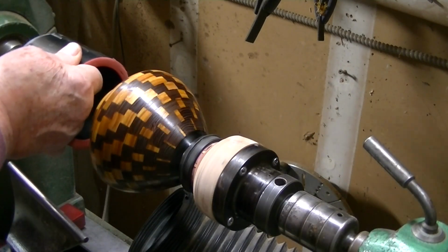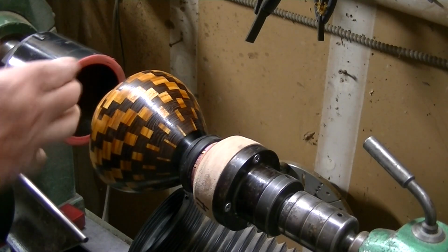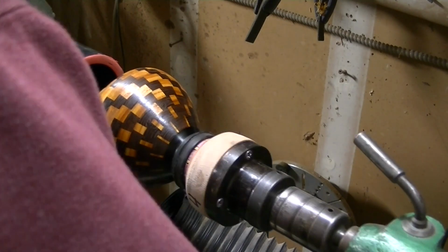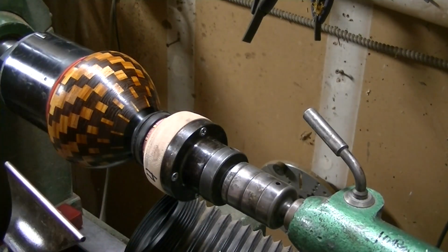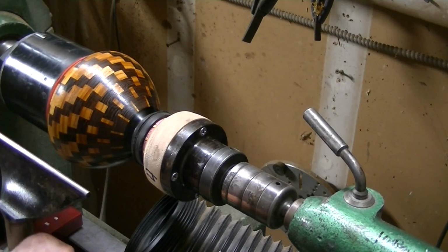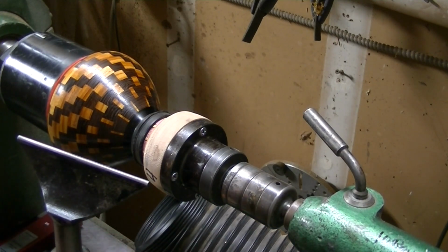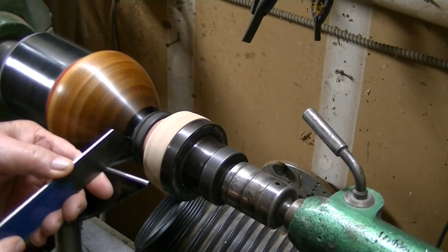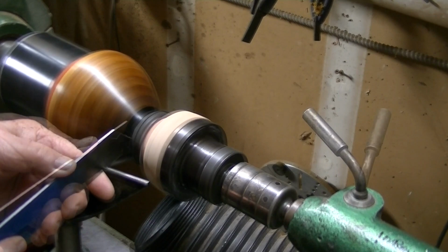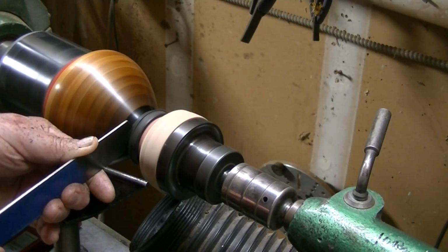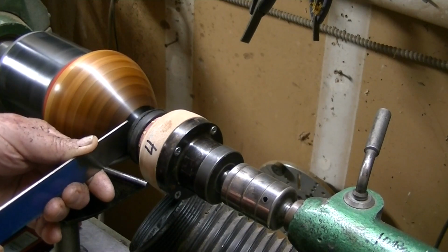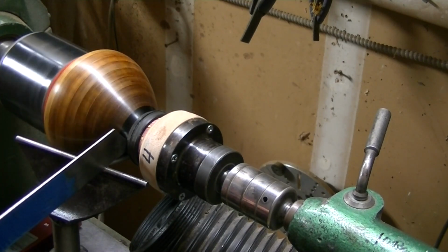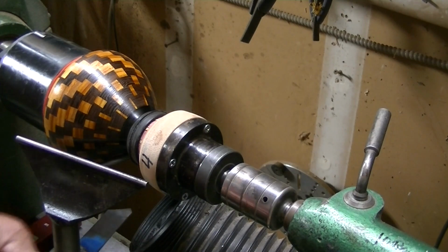So here's my vacuum chuck going on. This is a custom made one I made that's right for this size of a project. And when I push this in with my tailstock and lock that down, I know that I am dead center. So now it's a matter of parting the vessel free from the faceplate. Back to one of my thin parting tools and overlapping cuts, and I take quite a bit of time to do this. I do not want to push across this. I want to simply hold the tool, allow the wood to come around and cut itself. I don't want to displace the project against the vacuum chuck. Well, eventually we get it parted off.